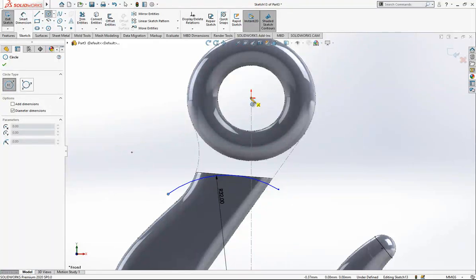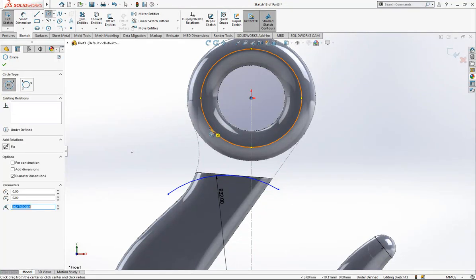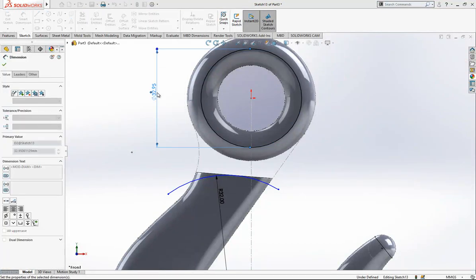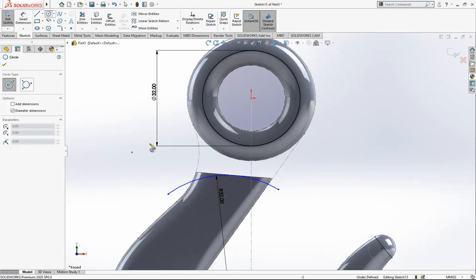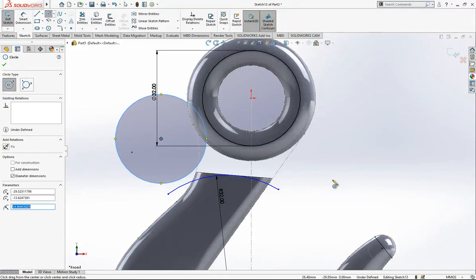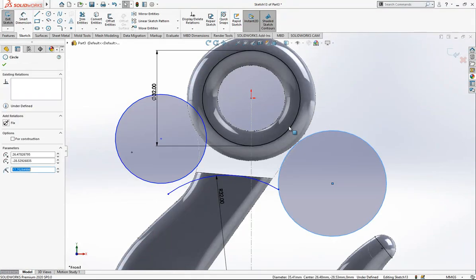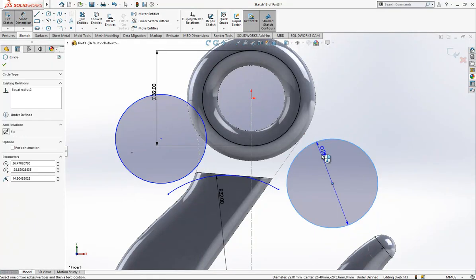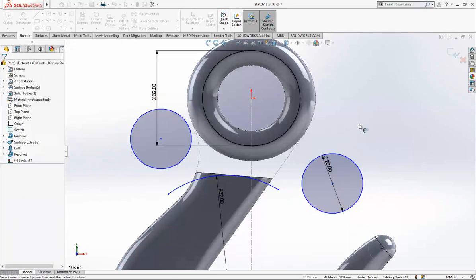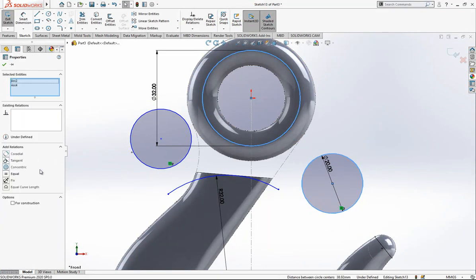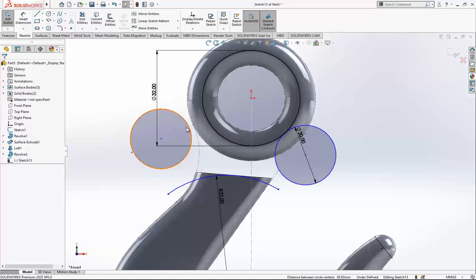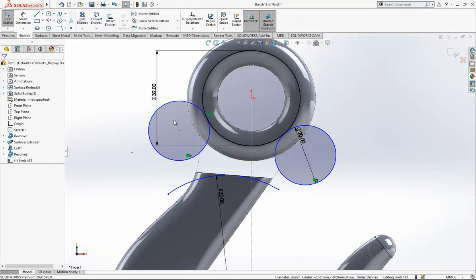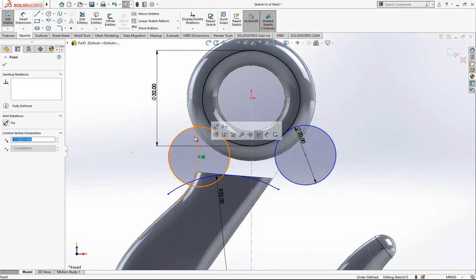And then later on, I'm creating here one circle, which will be 32. And here, 2 times circle. These both will be equal. And here, the value is 20. And I'm saying to my program tangent, tangent. Here I will pick this point.